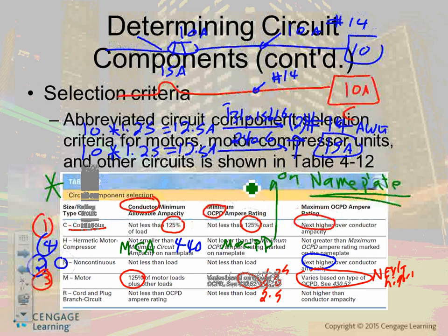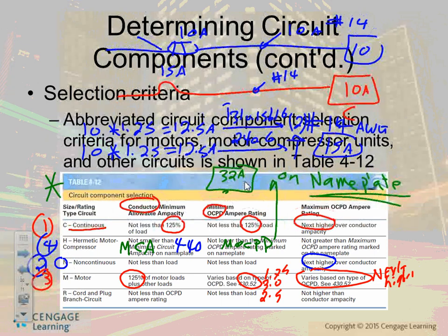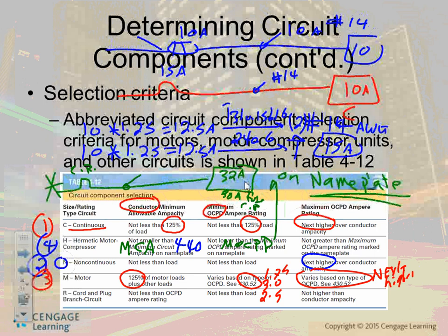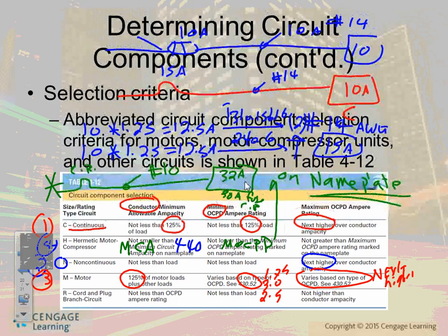So what do you do? Here's my AC, gentlemen. It says 28 amps minimum circuit ampacity and 30 amps fuse or circuit breaker. So you come over here and put your circuit breaker, and what conductor can carry 28 amps? No multiplication, nothing. Just take the 30 amps. I can guarantee you it's number 10. I'm sorry, I wanted 28, to make it typical. 28. Number 10.